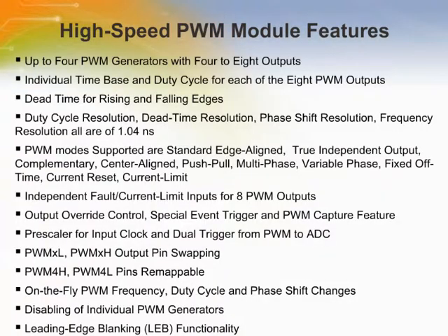The High-Speed Pulse Width Modulation module on the dsPIC33FJ06GS101 and the dsPIC33FJ16GS devices supports a wide variety of pulse width modulation modes and output formats. This pulse width modulation module is ideal for power conversion applications. The module contains 4 pulse width modulation generators. The module has up to 8 pulse width modulation output pins: